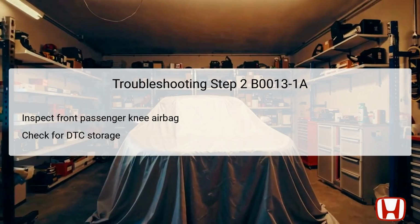B0013-1A, you need to inspect the front passenger's knee airbag closely. First, ensure that the knee airbag inflator connector is disconnected. Then, you should consult the vehicle's systems to check for any recorded DTCs.